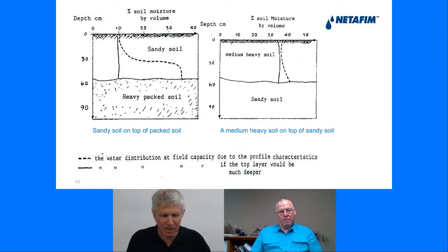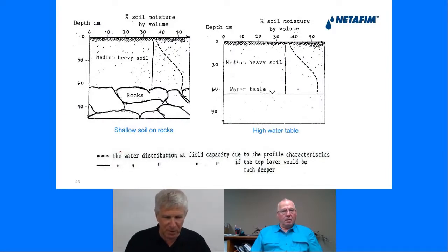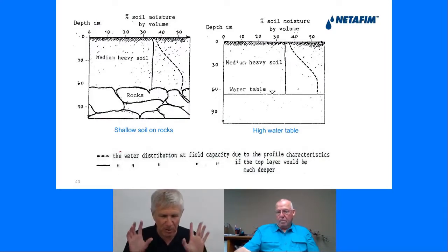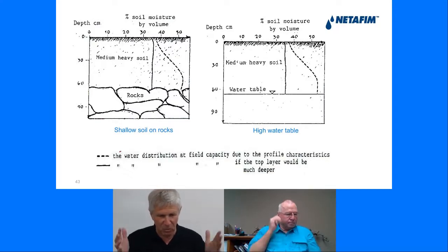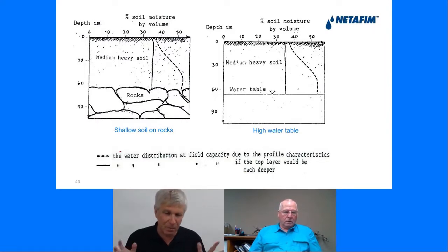And another example, which doesn't represent different soil types, is a shallow water table. Again, if you install SDI in a shallow water table, and especially if this water table is saline, you can create tremendous damage. So you need to know what soil layers you have in the soil profile. You need to know where the water table is located in different places where there is a shallow water table, because according to this, first of all, you determine if you can put SDI, and second, where to put it and how to do the irrigation scheduling.